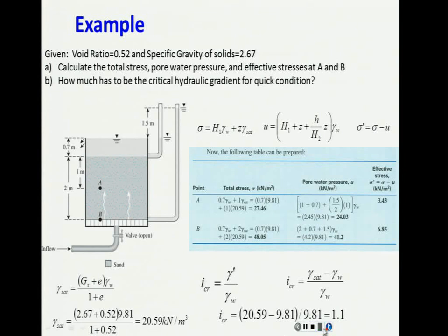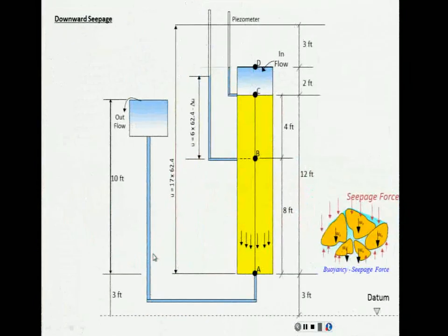Now the question could be, is that happening? Well, you can calculate it. Divide this gamma total 1.5 by 2, and you will see that it doesn't happen, because 1.5 divided by 2 is 0.75. If the seepage is bigger and this goes, let's say, up to 2.2, then it will be exactly there. But for that I have to have more inflow of water. That's for upward seepage. For downward seepage it is the opposite.